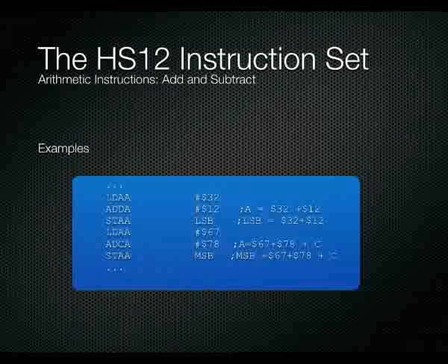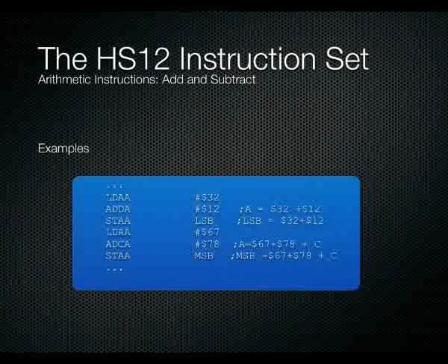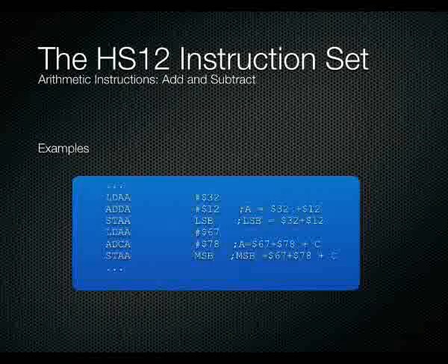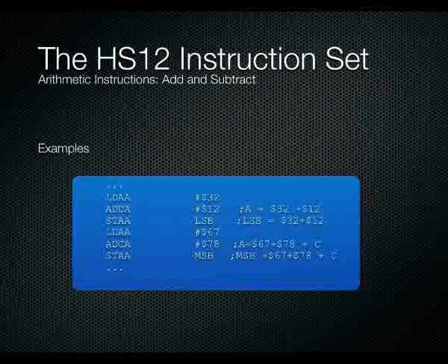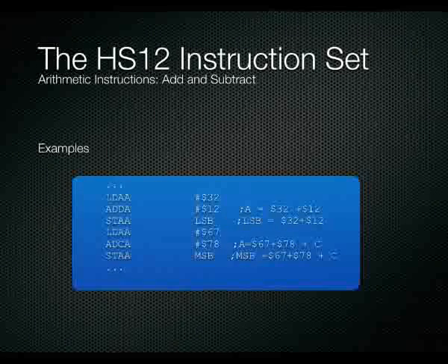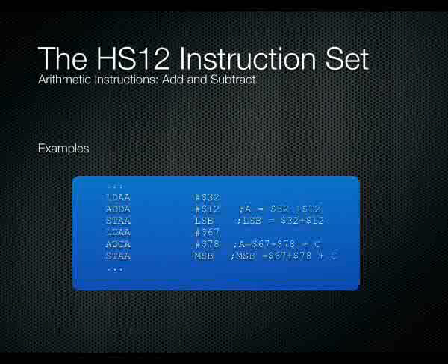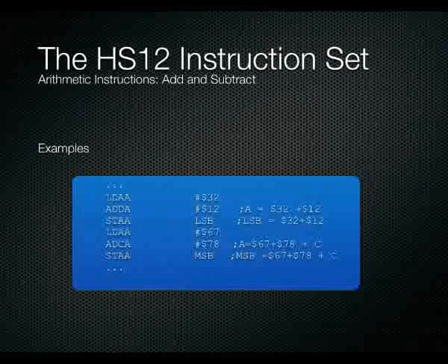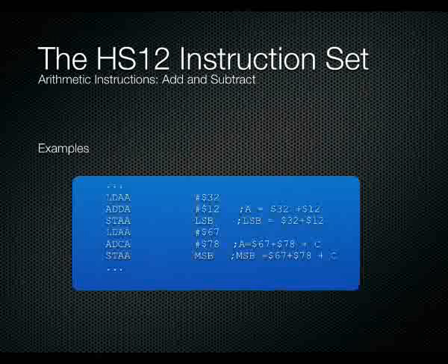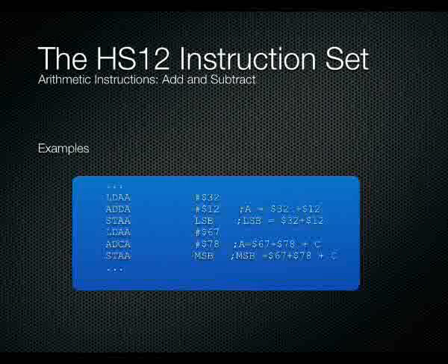So there is an example of adding a 16-bit number together, but doing it with two separate 8-bit additions. In reality, if you're going to do this on our processor, you'd simply use accumulator D and add it as two 16-bit numbers. But here's an example of how you might deal with multi-word numbers. If there were a 32-bit number made of two 16-bit components, you'd do it the same sort of way, but you'd be using accumulator D instead of accumulator A.